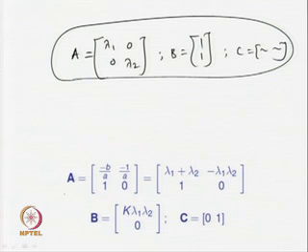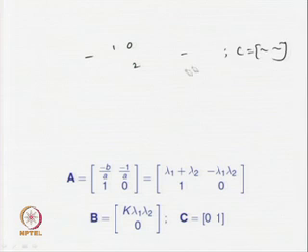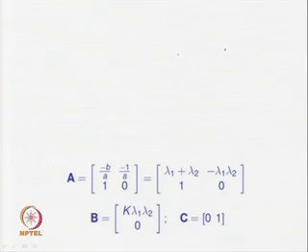Okay. Now, when A, B, C are found in this fashion, subsequently we can make use of these constants and the state and output equations for deriving analytical expressions necessary for identification of the parameters of the second order plus dead time model.